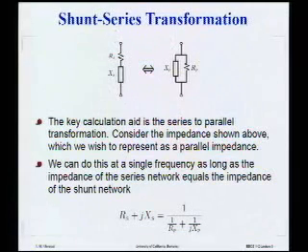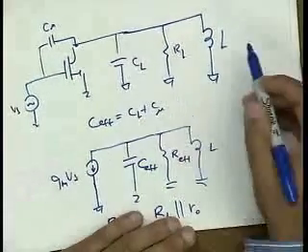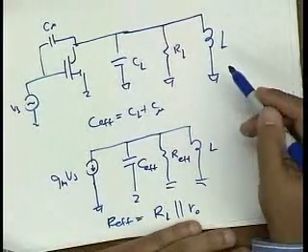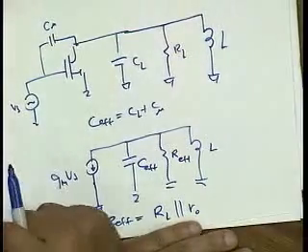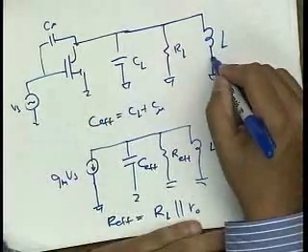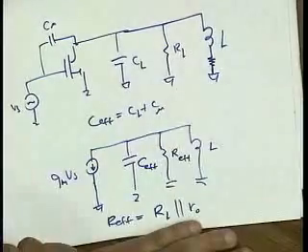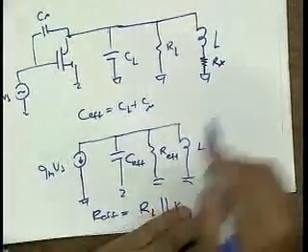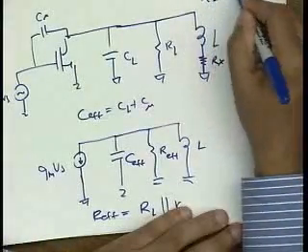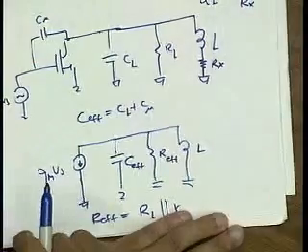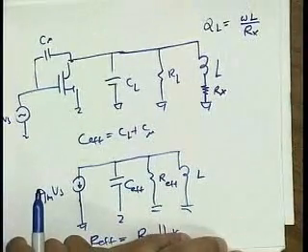Okay. Let's come back to this picture here. In this picture, I go out and I buy this inductor, and the manufacturer tells me, sorry, it has a finite quality factor of, let's say, 30. That means that there's a resistance in series with this inductor. Let's call it Rx. And QL is omega L over Rx at some frequency that you're interested in.